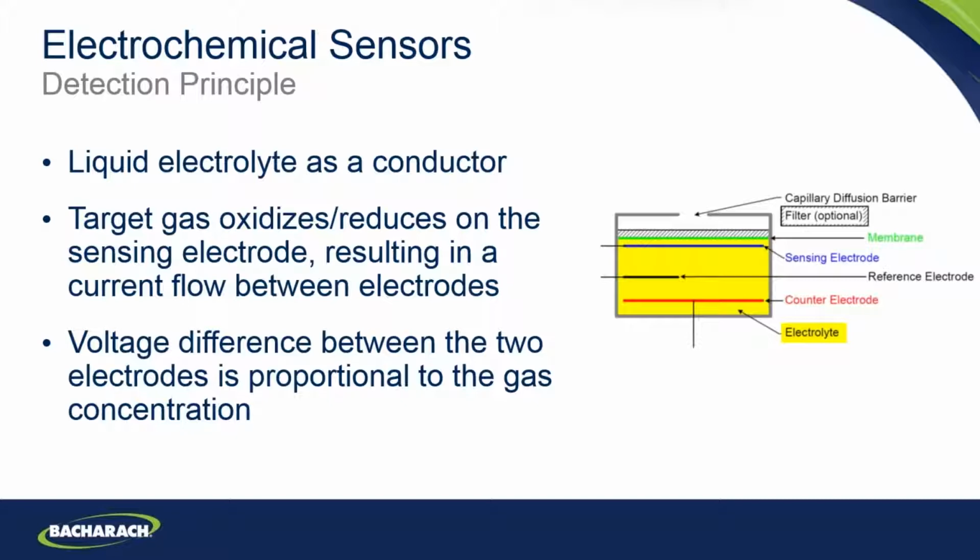One thing to bear in mind with electrochemical sensors is they are typically life limited. Most of the sensors available in the market will have a lifespan in the region of 2 to 3 years, at which point the sensor needs to be changed out and replaced.